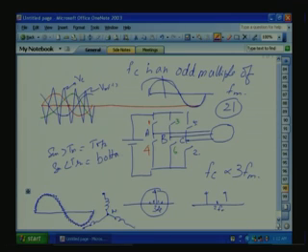So, the current is nearly sinusoidal and the harmonics are shifted to the high frequency side. But for sine triangle PWM, we require a triangle waveform and a sine wave, which can be generated. For very high frequencies of operation, where FC is very high, the synchronization, that is the zero crossing of the triangle and the sine, we do not have to worry.